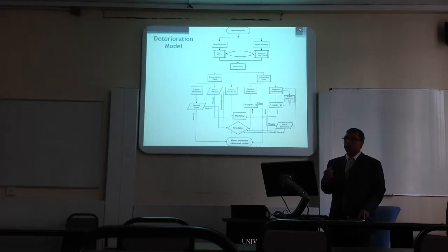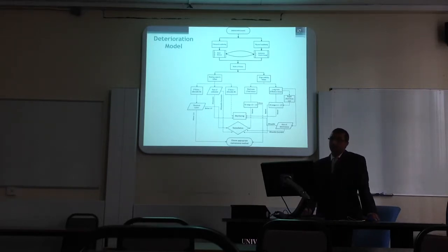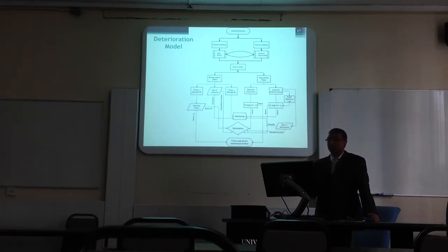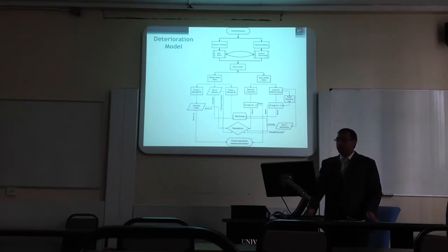So to start, you can see the chemical weathering and physical weathering are the basics which actually affect or initiate the deterioration. Chemical weathering is due to water and minerals, and physical weathering is due to settlement and volume change. However, these occur concurrently. They cannot occur single-handedly; chemical weathering cannot occur singly, other than with physical. They occur both concurrently. So the modes of failure are bearing capacity failure and slope stability failure.